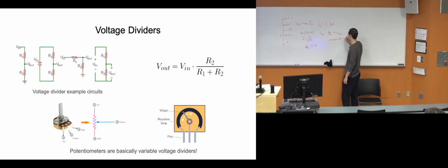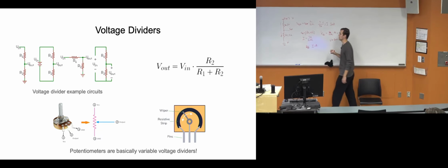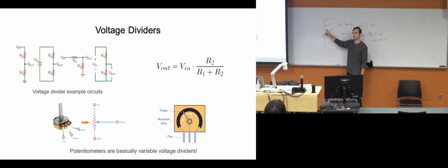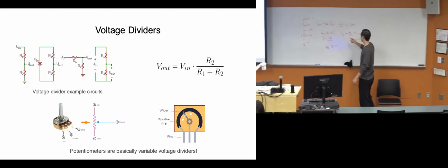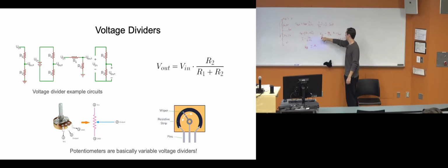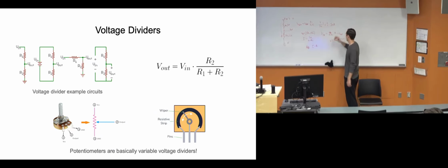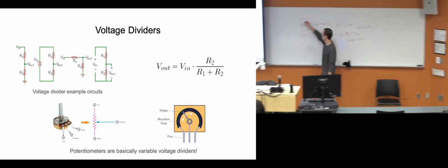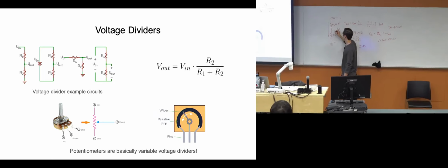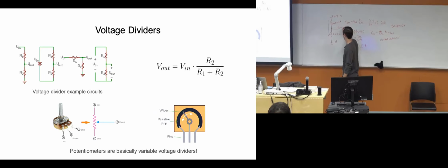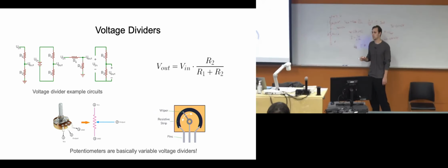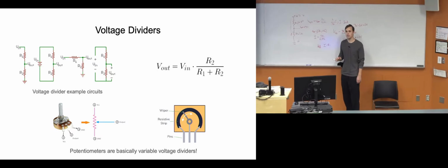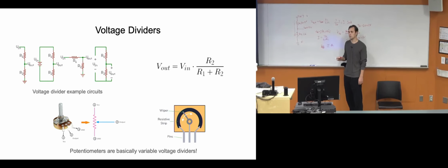So that means the voltage drop is 1 volt across here. Does that make sense? So then we can take the total VDD that we have, 3 volts minus 1 volt equals 2 volts. So we know 1 volt dropped over this. So we know this node must be 2 volts. Does that make sense? I feel like that was a little convoluted. OK.